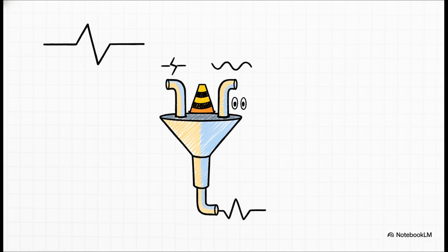But here is the trap. And it's a good one. If they ask for frequency deviation in a PM system, you must multiply your phase deviation by your modulating frequency. Read the variables carefully. Ensure you don't mix up the FM frequency deviation constant with the PM phase sensitivity constant. They love testing that distinction.